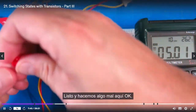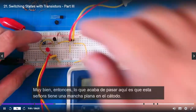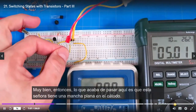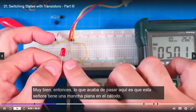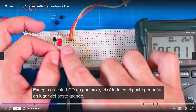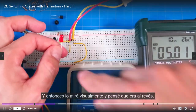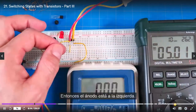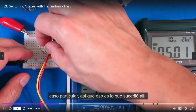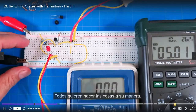And do we do something wrong here? Okay. All right, so what just happened here is this. This LED has the flat spot on the cathode, except in this particular LED, the cathode is the small post instead of the big post. And so I just looked at it visually and thought it was the other way around. So the anode is on the left, the cathode is on the right, the anode is the big guy, and the cathode is the little guy in this particular case. So that's what happened there. And again, that's why you've got to test these things. Sometimes they just make them a different way. Everyone wants to do things their way.